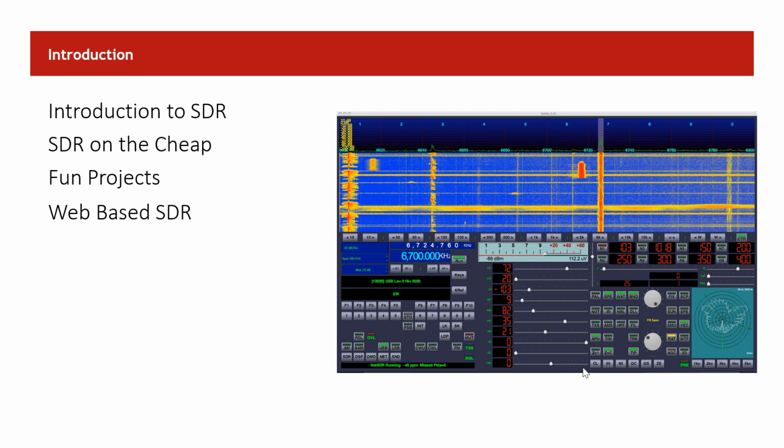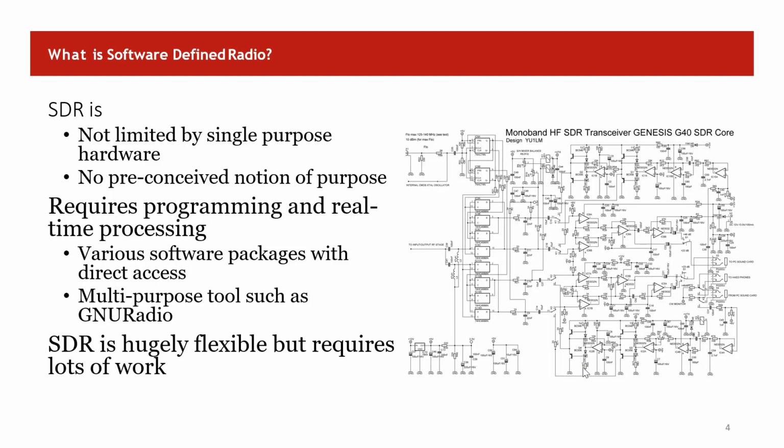So that is the software-defined radio, which typically listens to the entire spectrum in the air, and then provides us the digital content, or the digital data. It takes whatever analog traffic is floating around the air, converts it into the digital medium, and displays it to us with the help of specifically designed drivers, software, and all. So this is the basic functionality of the SDR.